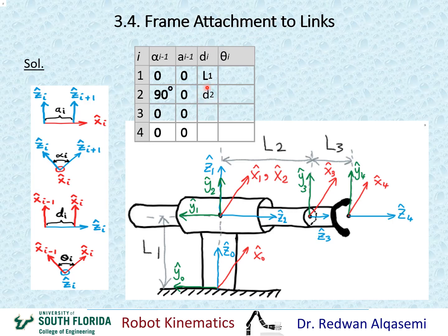So this is a variable, all right? This means that we're expecting theta 2 here to be a constant. Since the variable is right here for the prismatic joint, that means this would be a constant. And since this is a constant for the revolute joint, joint 1, this will have to be a variable. And we'll see this once we start working on this column.